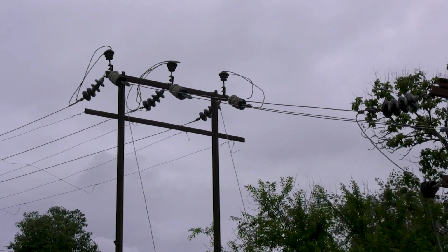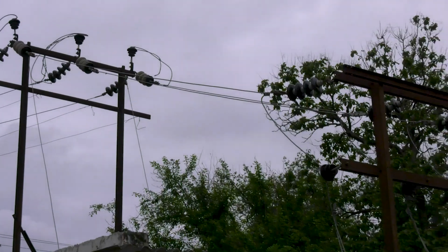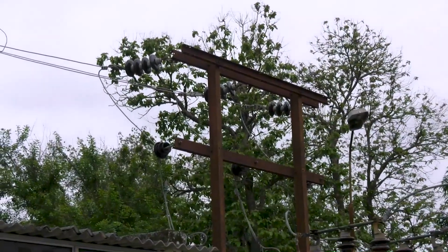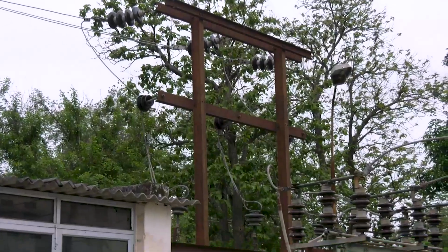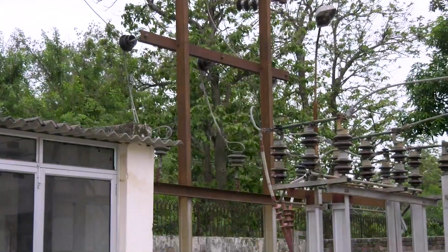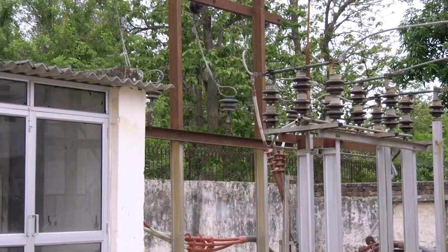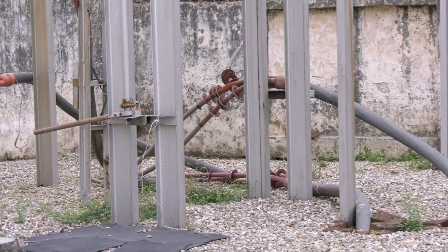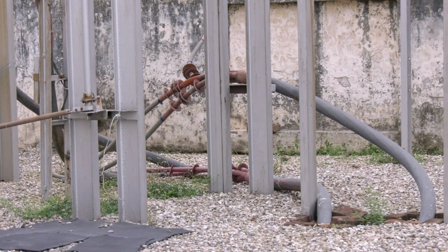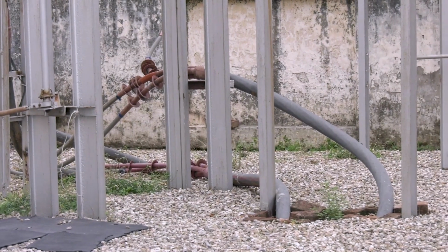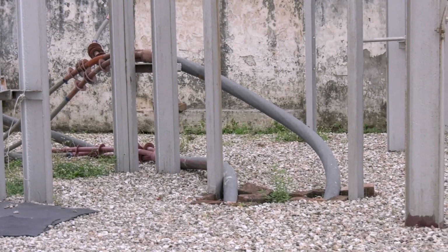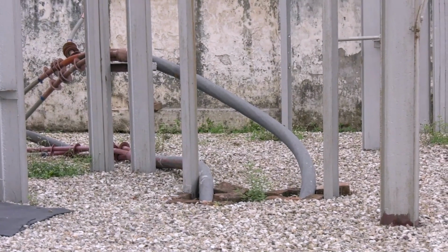Initially, the campus relied on a 33 kV overhead line, which was prone to frequent tripping and disturbances, especially during the rainy season. To ensure a reliable power supply without seasonal disturbances, we laid a dedicated 33 kV 3C × 300 sq mm, 5.4 km underground cable from the 220 kV Ramnagar substation to the 33 kV IIT Roorkee substation.